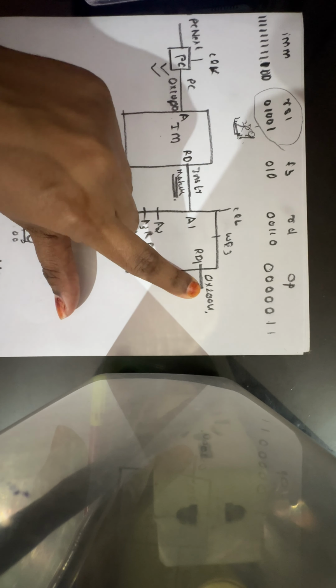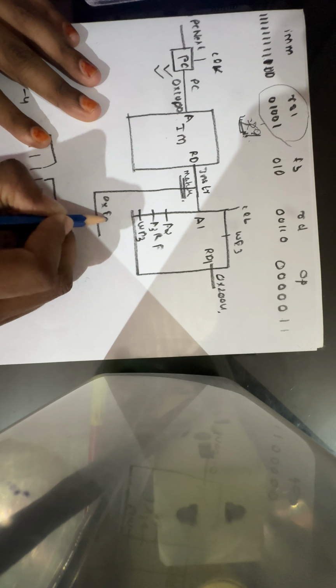The content in RS1 was this. Now again, you have the 0xFC, you use this extender here, and we got this immediate extended value, that is 0xFFFFFC. You got this immediate extended value, which is 32-bit. Now what we have to do, this -4 you have to add in the ALU. In the ALU, you have to add this -4 with this value. That is the next step.